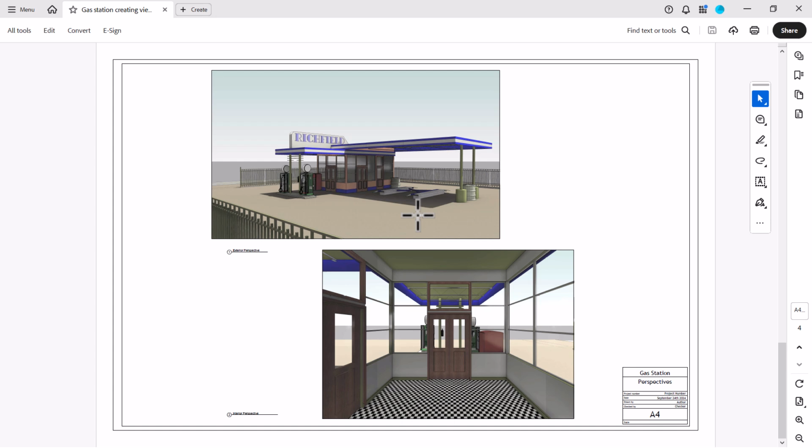And just don't forget, when you print these PDFs, you want to make sure that you are printing them to scale. These are scaled drawings, most of them, obviously not the perspectives that we happen to be looking at. And for our purposes, we're going to use these as a check print. So we're actually going to reduce them onto 11 by 17 color laser prints.